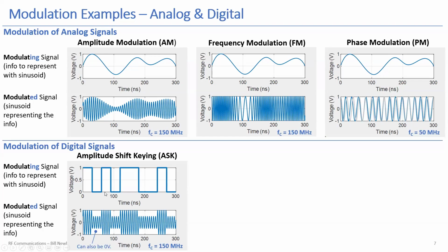This is just for visualization purposes, but know that when you really have a modulating signal, you apply that directly to a sinusoid, typically there's some pulse shaping, so you don't have these very sharp transitions that spread the width in the frequency domain, which we'll talk about, wider than necessary. So that's amplitude shift keying.